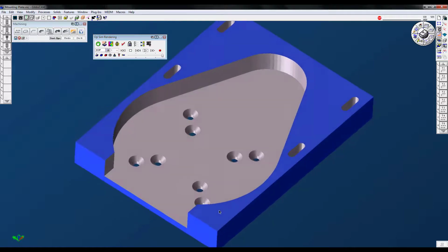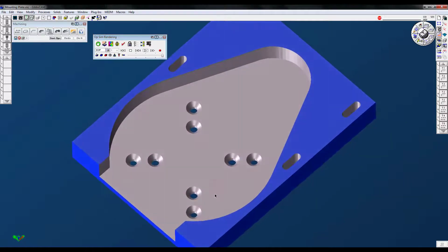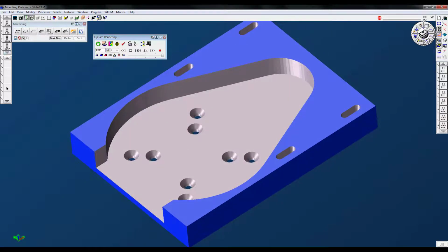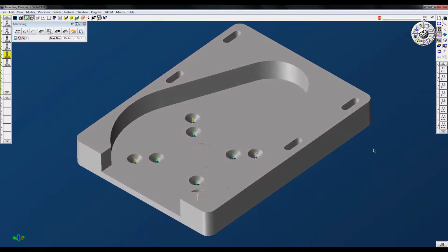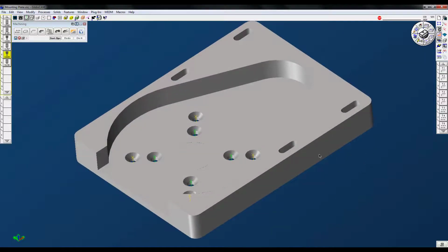we can see that we get all of those holes drilled and countersunk. And GibbsCAM has automatically created those tools for us. So drilling holes inside of Gibbs is really, really easy. All right, so here you can see that we have a pretty complete part programmed. It's great. Just really briefly, because we're running out of time here, I want to show you how a lot of these fundamentals roll over into some of the more complex Gibbs applications.